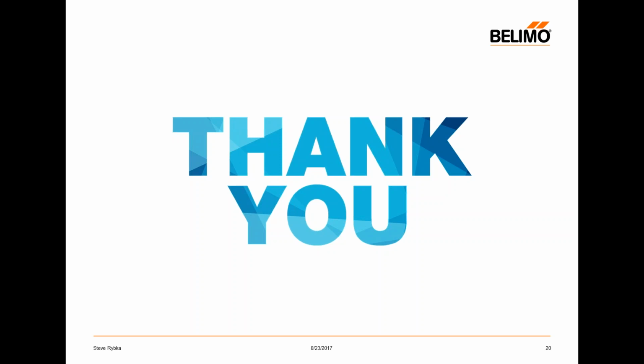Okay, next question. What would be the best application for the energy valve from Belimo? AHU units only? That is where the bulk of the intention was emphasized. Yes, air handler units, they're the bigger consumers of chilled water, so they're going to be the units that can be optimized the most, and yeah, air handlers are really the primary suspect, if you will.